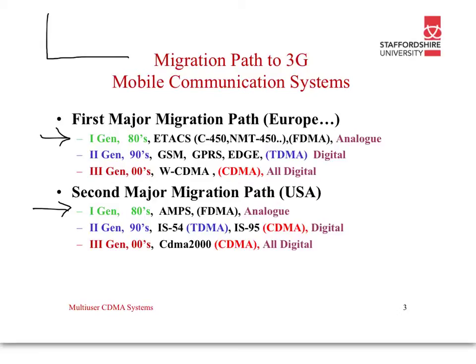So if I use this graph here, if this is frequency, then we would split the channel up into smaller bands, so there would be a lot of wastage because we needed some space between these bands, otherwise one user would interfere with another. Hence the number of users, or K, is limited in frequency division multiple access schemes by the number of frequencies. Hence this wasn't a very popular system. Another reason why it wasn't very popular is it wasn't very secure, because somebody could listen in to the particular frequency and they could hear the message being transmitted.